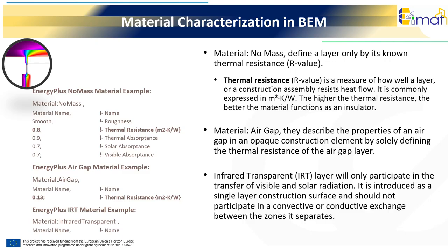Accurate thermal resistance values allow BEM tools to model conductive heat transfer correctly, influencing heating and cooling loads, energy use, and occupant comfort. Air gaps in a construction are defined similarly to no-mass material. They describe the properties of an air gap in an opaque construction element by solely defining the thermal resistance of the air gap layer. On the other hand, an infrared transparent layer will only participate in the transfer of visible